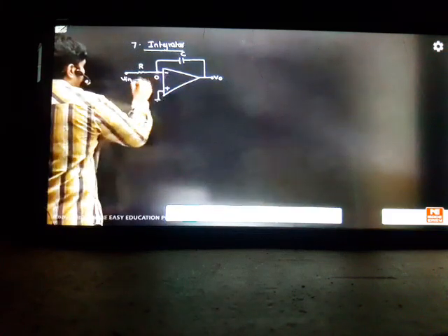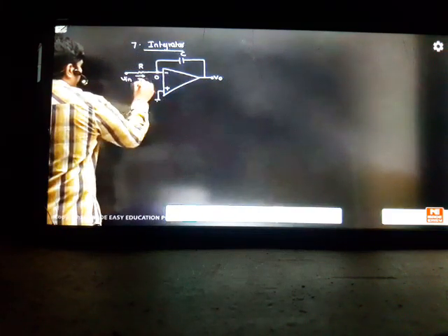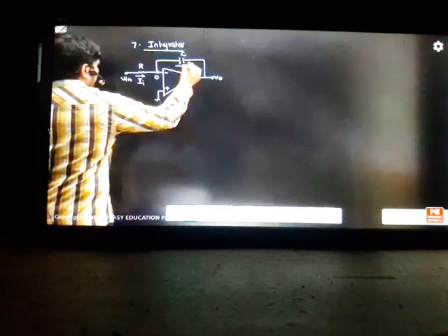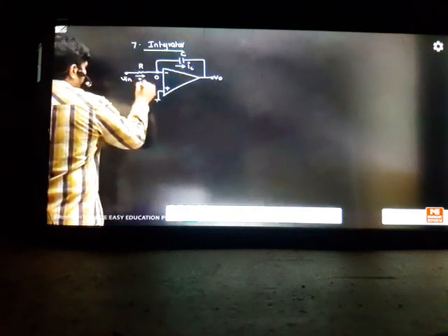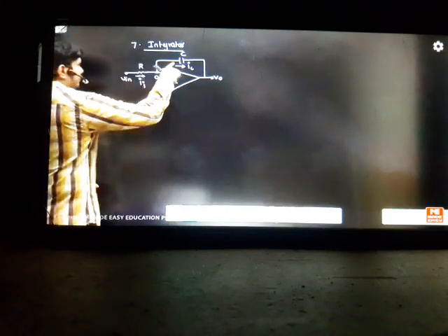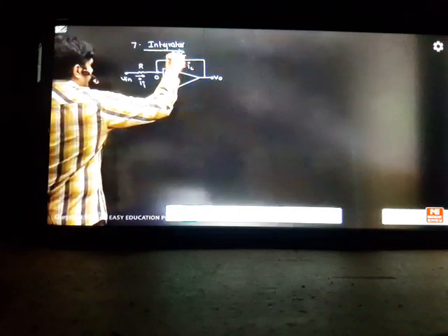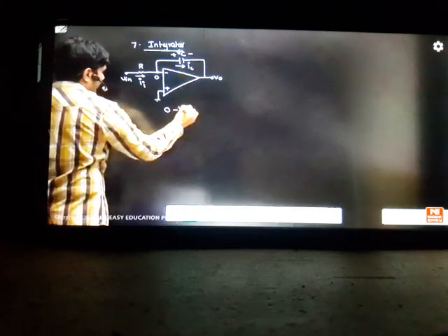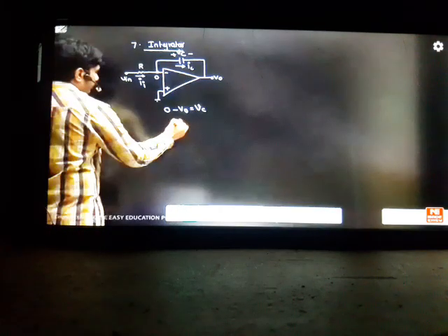Capacitor I have taken. If you take a capacitor, you can charge the current. This current I, you take, will be IC because we have to apply AC here. So let us use the small letters here. We are using AC analysis here. Your I, IC current. Capacitor will charge. AC wise you can charge it. So if the current goes to the C value, you can expect the output, here the VC voltage will be provided. So 0 minus V0 will become VC. So output will become simply minus VC.